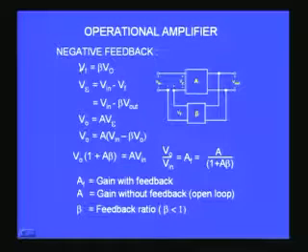as the feedback voltage Vf, and the V epsilon, which is a voltage actually connected across our amplifier, is what I connect outside, V in minus whatever I have given as a feedback Vf, because they are in opposition, 180 degrees out of phase. But Vf is beta V naught, therefore I substitute here V in minus beta V naught, and we also know from this amplifier characteristic V output is A times V epsilon, which is the actual input connected at the terminal. So V output is A times V epsilon, and V epsilon is V in minus beta V naught.